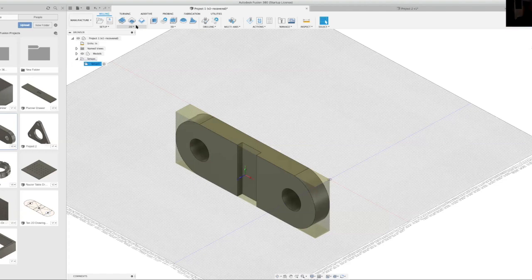So it'll go through and carve out massive amounts of material very, very quickly. Yeah. And then it comes back with the finishing pass, and it does either the climb or the conventional. Remember we were talking about that the other day because of the backlash on the machine? Yeah. And it does a really, really clean job even on the Shapeoko. It's amazing. It was holding tolerances to about 1/10 of a millimeter when I was testing it.